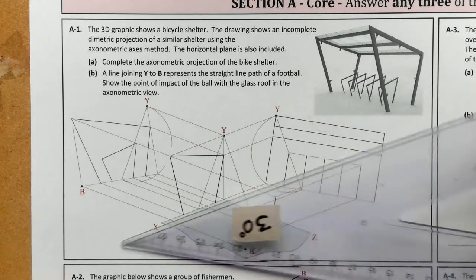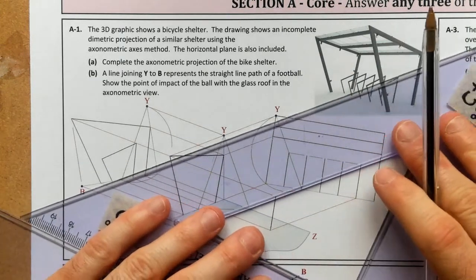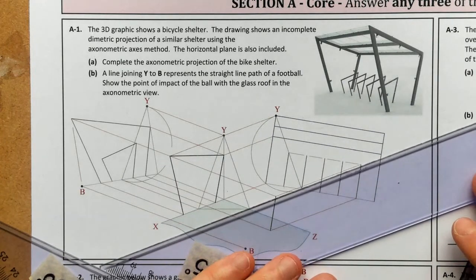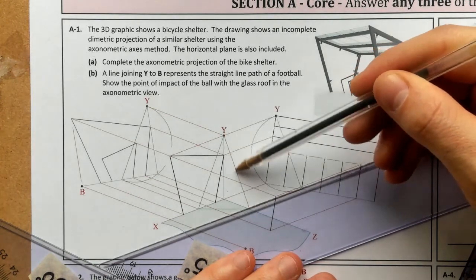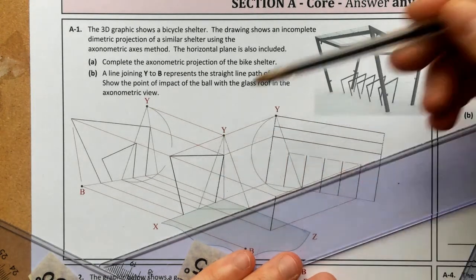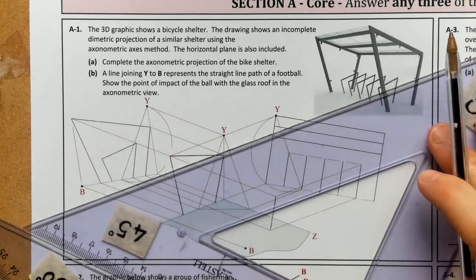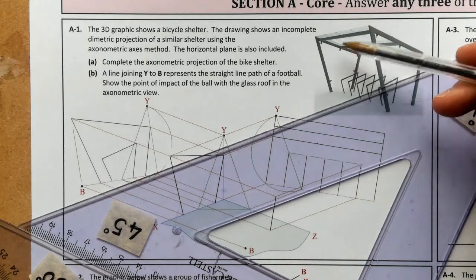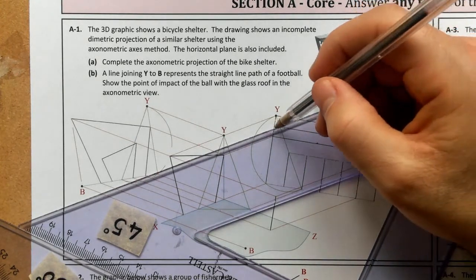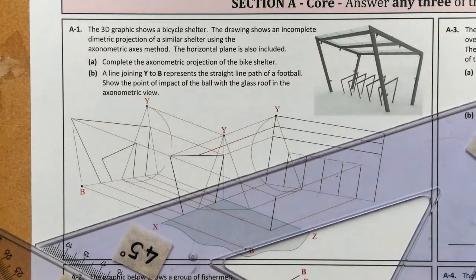To complete them, what we're going to do is a little bit of sliding set squares. Using your set squares, line it up. Obviously you're projecting at the angle they've given you. It's actually perpendicular to the plane line here, the axonometric plane, so it's perpendicular on this side and perpendicular there. I'm going to project that as best I can. There we have it. At this point I'm going to locate where the middle line is. You can see the middle height, which is up here, is in this position. So I'll project that across, and that will show me where it is hitting over here.